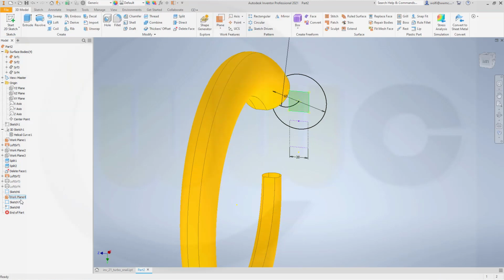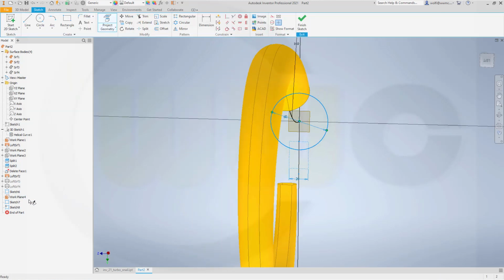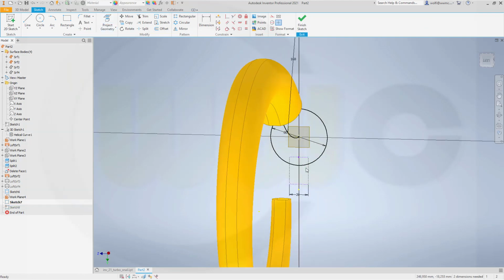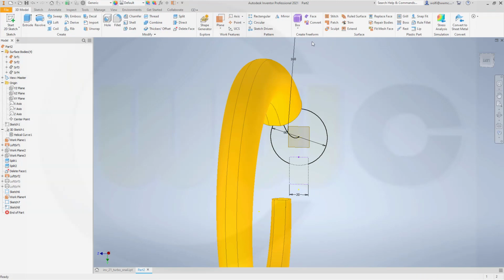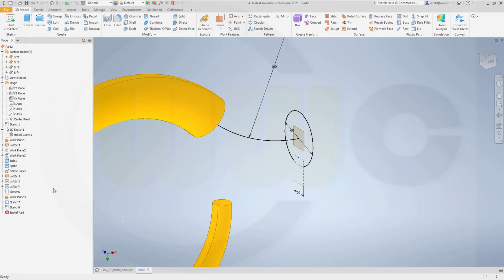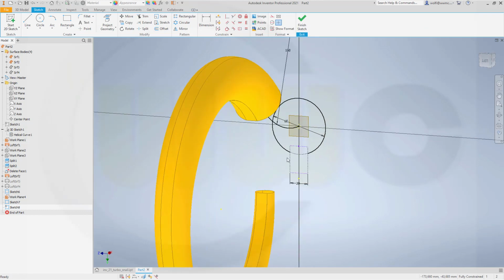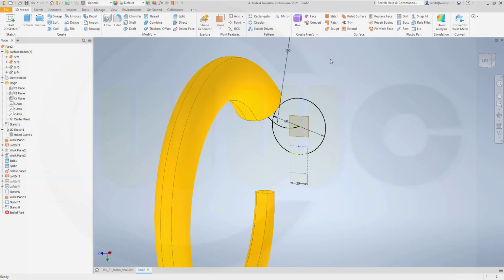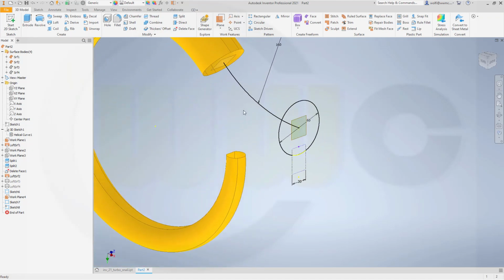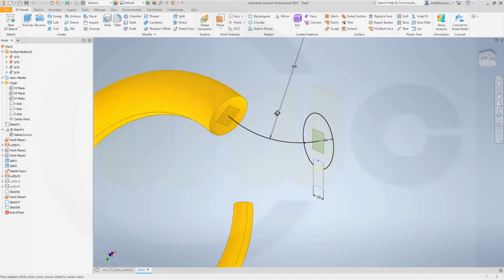Finish that sketch. Go back to the first one and put this one here on construction like this. And now that sketch is this one and that's this one, yeah. So this should be, of course, not for construction, like that. Finish that sketch, and now I should be able to do 2 lofts.